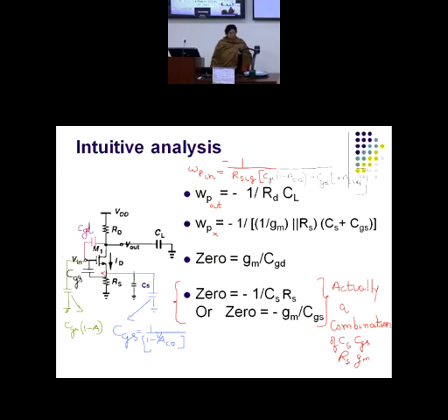Remember that. Okay? And if you are applying an AC source, then your source always has a resistance. So if your signal is coming from the previous stage, it would be the R out of the previous stage. Always remember that. So now we have omega P at the input node. I am finding out the time constant of each and every node. So time constant is R into C. Simple. So R will be R signal here.